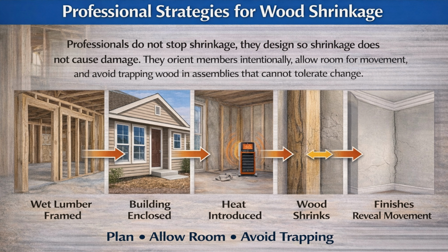Professionals do not try to stop shrinkage. They design so shrinkage does not cause damage. They orient members intentionally, allow room for movement, and avoid trapping wood in assemblies that cannot tolerate change. When buildings move after they are finished, this is almost always the reason. Wet lumber is framed, the building is enclosed, heat is introduced, moisture leaves, the wood shrinks, and finishes reveal the movement. This is not a mystery, it is physics.